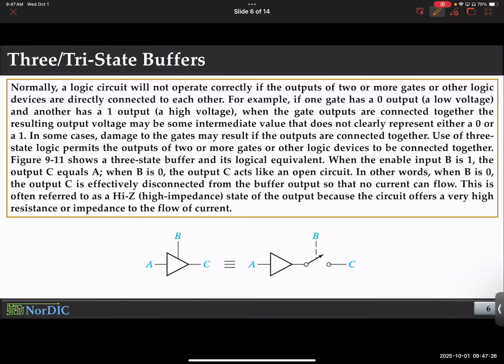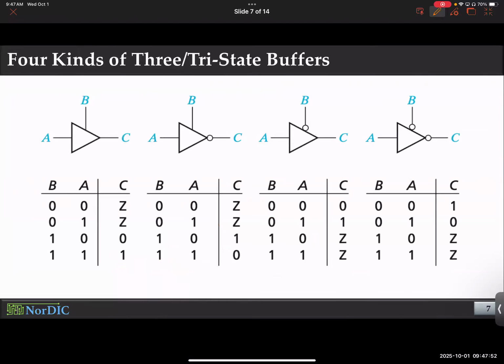So what this logic gate does is create a really high impedance between the output and input if you provide a certain select signal, 0 or 1, depending on how you design it. Otherwise, it provides a low impedance, really low resistance path, which basically connects the input to the output. So you either connect it or disconnect it. And you will encounter situations where you say, hey, I don't want to make it 0, I don't want to make it VDD, I just want to disconnect it. And that's how you do it using a tri-state buffer. Okay. Are you still with me?